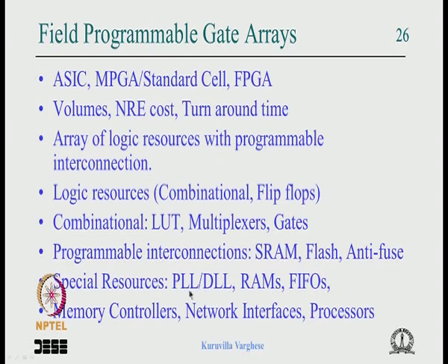nowadays. Mainly all the FPGAs use PLL, phase lock loop, which has advantage over DLL. Maybe we will briefly look at it, though there is no particular reason, because the current FPGAs use PLL. Then the memories, RAMs, the FIFOs, the same RAM can be used as FIFO with additional logic. Memory controllers, sometimes high end FPGAs need, since it has a lot of computational possibilities or option of implementing complex computation.